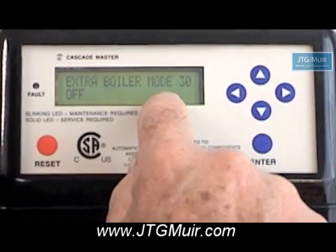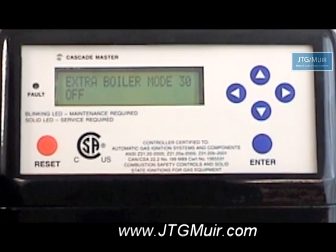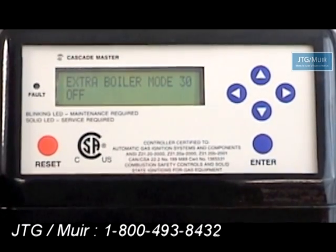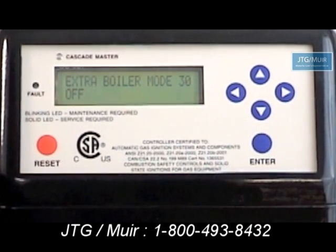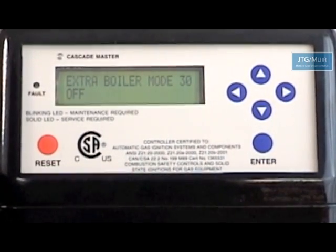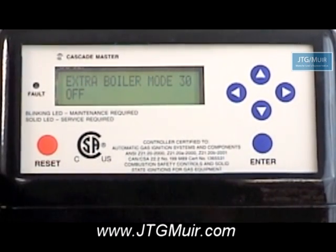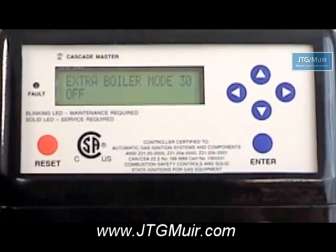The extra boiler mode, number 30, off. This function allows the Elite boiler, if it cannot keep up or a series of them cannot keep up, to send out a 120 volt signal at a predetermined percentage of output to fire up an older existing boiler to help on the few days a year when there's a high demand. Also, if for some reason the boiler is down, it would allow the other boiler to take over as a substitute. Normally that's on off.